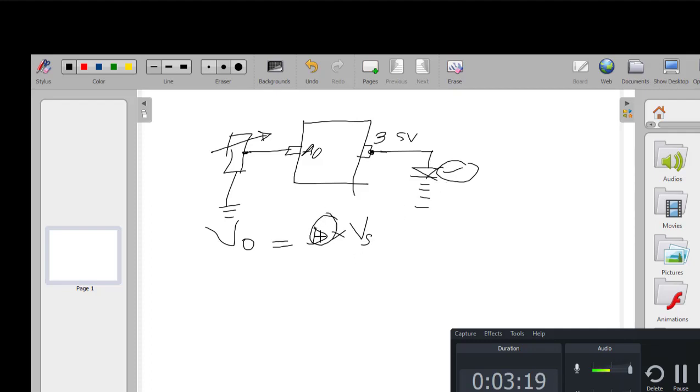And now this duty cycle will be a value that ranges, as we explained about microcontrollers, between 0 and 255. So any value that lies between 0 and 255 will be a fraction multiplied by Vs. Now remember that the duty cycle is actually a percentage, and when we say that counting starts from 0, the overflow value is 255.